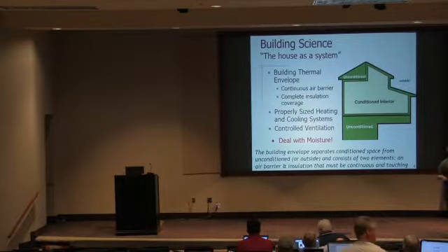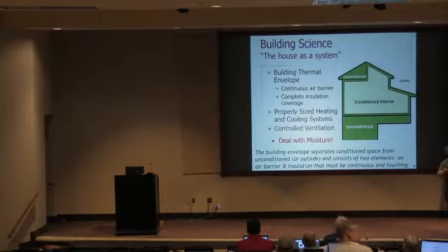You know, we rely basically on HVAC equipment to run for a long time, to move a lot of warm, humid air over the coil, and to wring moisture out of that warm, humid air to dehumidify. If you have short run times, it takes about 15 minutes of run time for that interior coil to reach the operating state where it starts to effectively dehumidify.